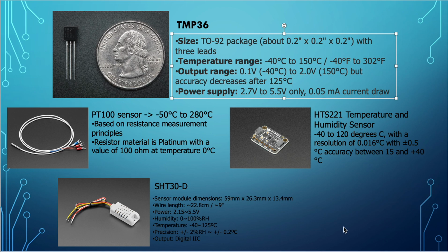So for example, we have different brands, different products of temperature sensors. TMP36, we looked at it, and we saw how to find the information through the internet, how to find the compatibility with the embedded systems, what is compatible and what is not. Then we check the ranges and the properties of each sensor to find out which one is okay with the requirements the engineer has to build for, right?